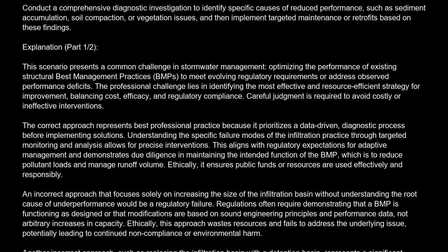The correct approach represents best professional practice because it prioritizes a data-driven, diagnostic process before implementing solutions. Understanding the specific failure modes of the infiltration practice through targeted monitoring and analysis allows for precise interventions. This aligns with regulatory expectations for adaptive management and demonstrates due diligence in maintaining the intended function of the BMP, which is to reduce pollutant loads and manage runoff volume. Ethically, it ensures public funds or resources are used effectively and responsibly.